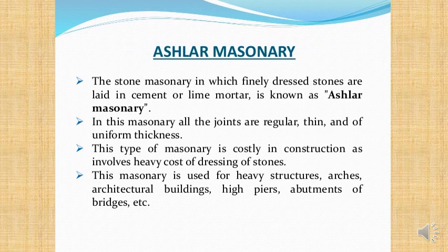So basically, I would say around 1,000 years ago, in Europe, and earlier than that, in the case of the Romans, ashlar masonry actually became more common. So ashlar masonry is the opposite of rubble masonry. Rubble masonry is where you get a rock, and regardless of what the shape is, you use that in your masonry wall. Ashlar masonry is where you cut the stone and you cut it into a shape that is regular. That's what's called ashlar masonry.